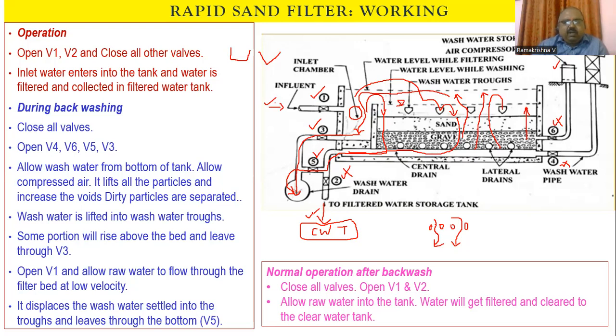And whatever raw water is used here for the backwashing is also considered as treated water. So the backwash water used here is nothing but the treated water. Otherwise impurities will get added up. So the backwash water quantity also should be added to the raw water for treatment.